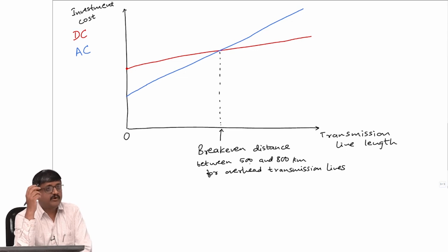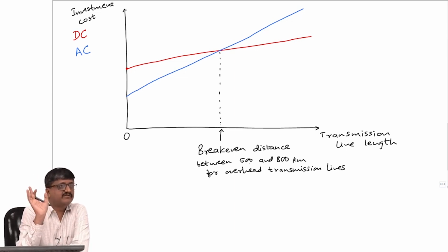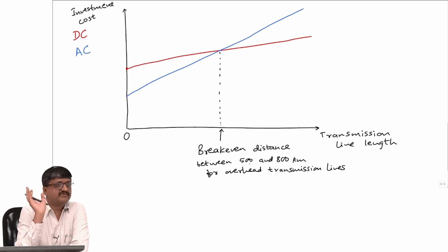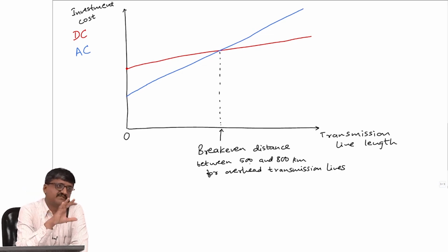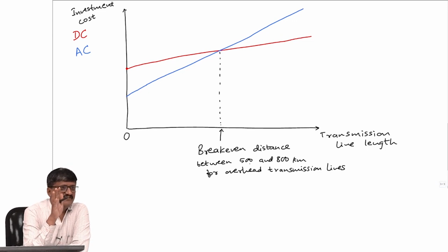Voltage level, yes. When you come to DC transmission, it is hundreds of kilovolts. Power level is thousands of megawatt. Your question is, what is the voltage level? That is irrespective of this. The voltage levels are similar to the voltage level of AC transmission.